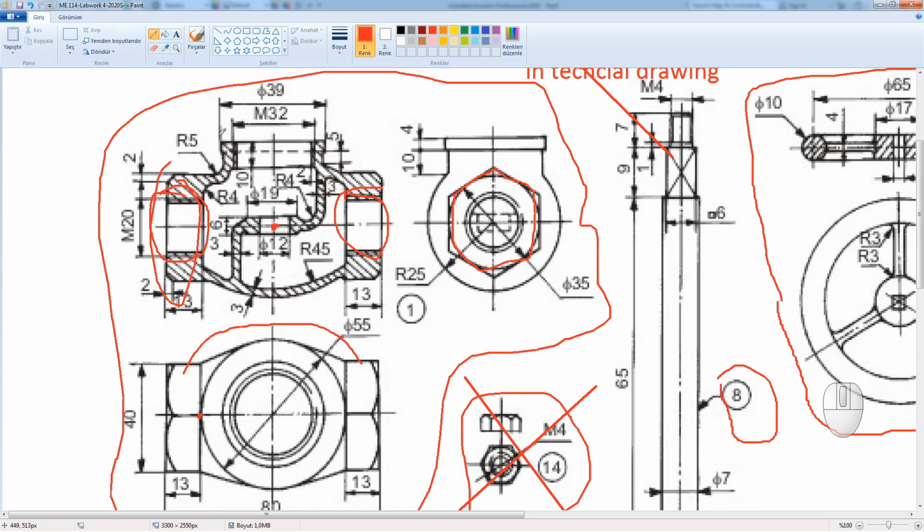After the hole creations, we are going to make the body part additions on the top side. After these additions, we are going to just create a wall additions inside of our body. For the body additions on the top side, we will just going to create a sketch on XY plane.